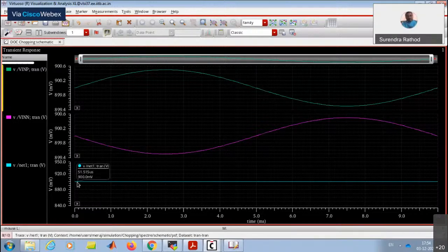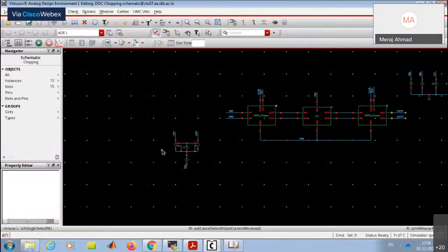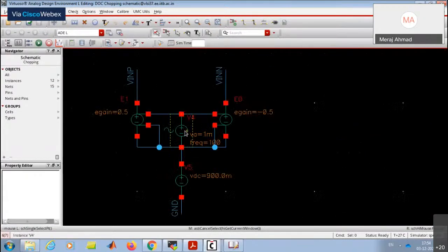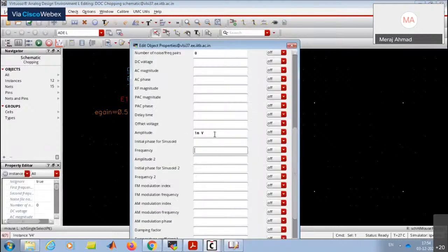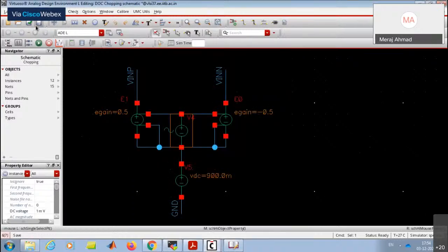So this is our signal, the DC reference. Since we are using a single supply, we need a DC reference, and we have this proper differential signal. If you take the difference, we will have a good proper signal. So our excitation signal is fine. And now let's see whether... let me just start with the one which we started with, the simple DC source.